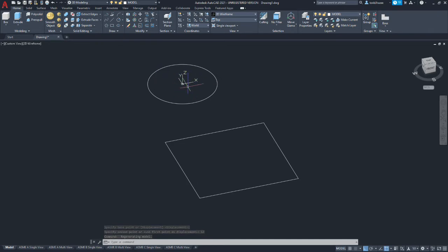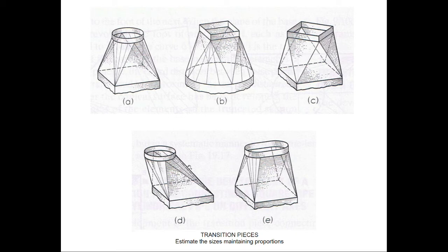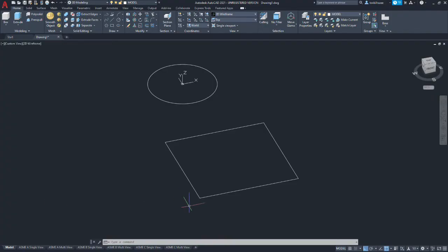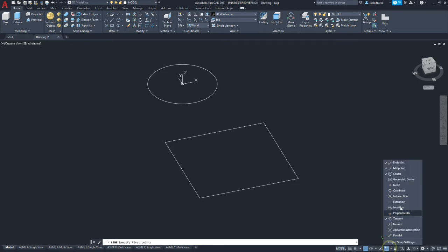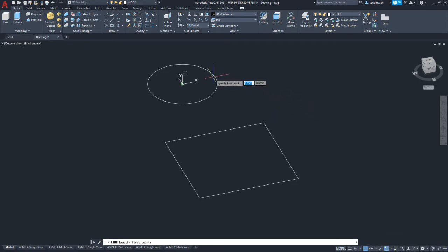Now we need to make an index point. Just like the other ones, we have these flat faceted sides with variable fillets transitioning to 0 radius. So we need to mimic that, and we need guide curves at the transition points for that. So let's go back to AutoCAD, and we're going to draw a line, and we need to make sure our object snaps include center, which that one does, and that ortho's on.